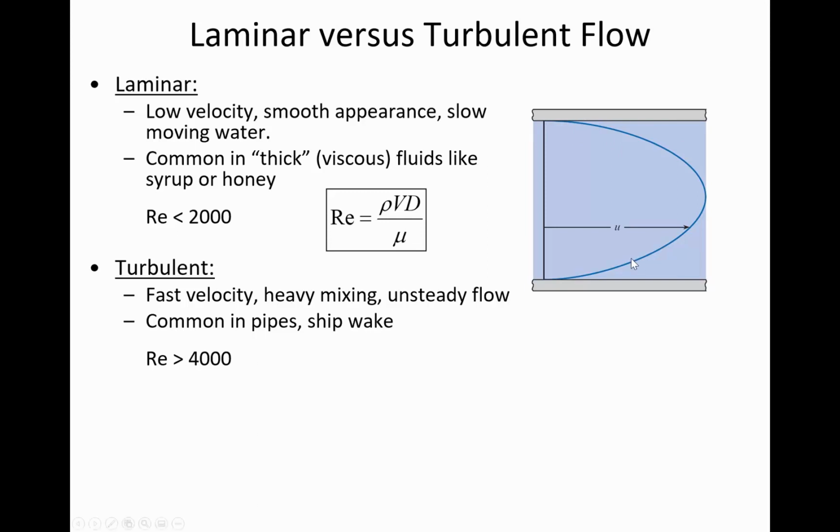And there's just a really gradual transition from the zero velocity water that's at the boundary of the pipe and the liquid, and then the further away you get from the edge where the pipe friction is being applied, then the velocity increases, and this has kind of a parabolic shape to it.